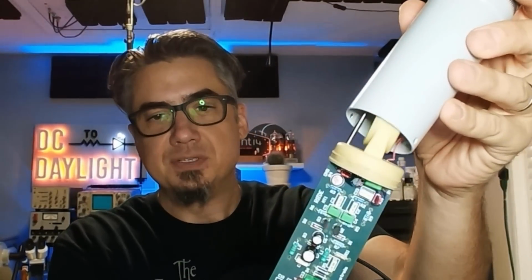I'd also like to take a look at this condenser microphone. So as you probably know, condenser is also another word for capacitor. And if we open this guy up, there's all kinds of interesting stuff in here. We'll take a closer look on the bench. But our microphone element here is actually a capacitor. So it has a metallized film on the front and a back plate. Okay, I think I have it backwards. Yeah, metallized film on the front. And those go down to an amplifier and this differential circuit that plugs into your recording gear.